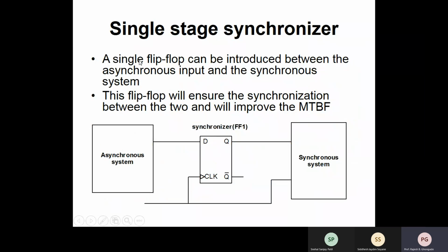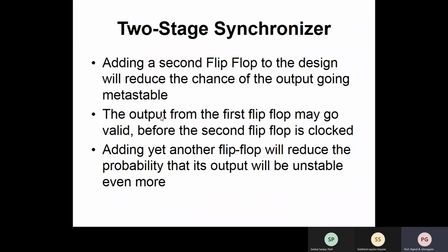It is a single flip-flop which you can introduce between the asynchronous input and the synchronous system. That is, this is the external world from where the input is coming. This is your clock system, and you are introducing one more flip-flop over there to ensure the synchronization. This will improve the MTBF.